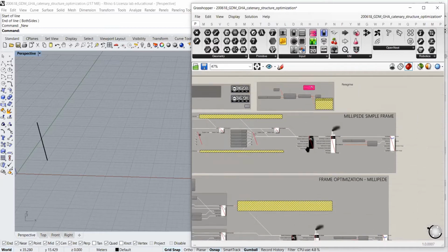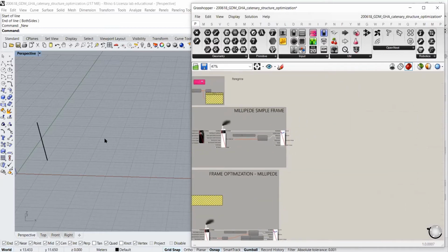Okay, so just pay attention to this and do it at the very beginning of your workflow. Don't do this later, because some things are not taken into account on the fly from Grasshopper. Okay, so I do recommend that you always start your Rhino template with meters. Even if you are not used to work with meters, some plugins like Millipede and also Karamba, they work with this system. Okay, so you must work with the same units.